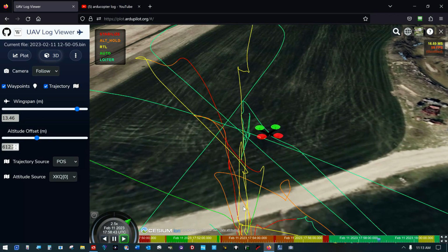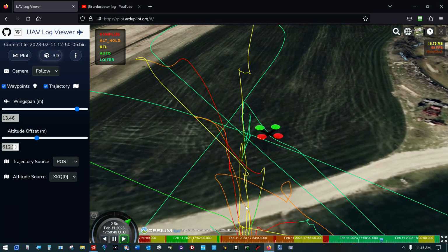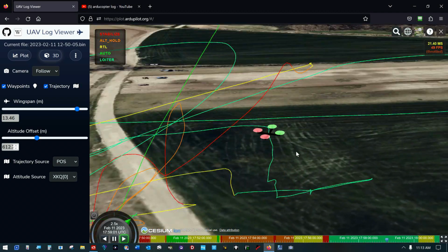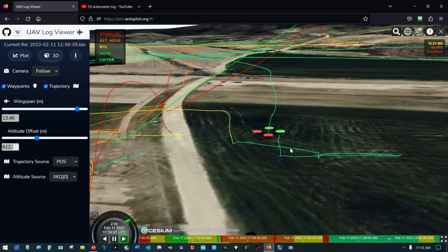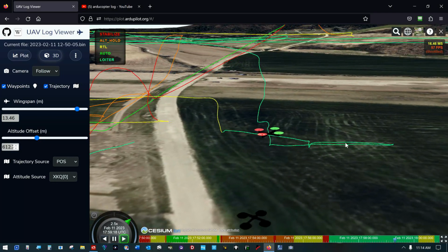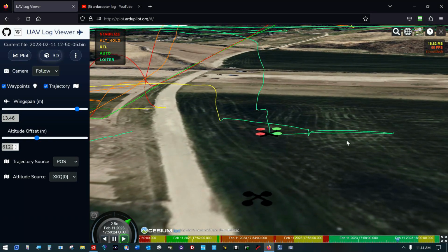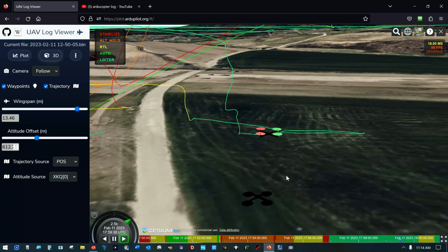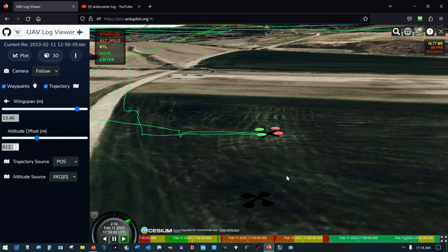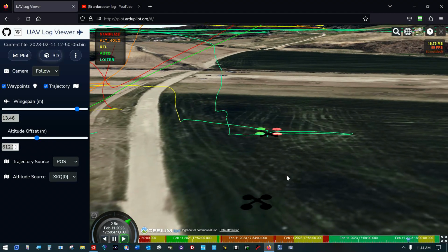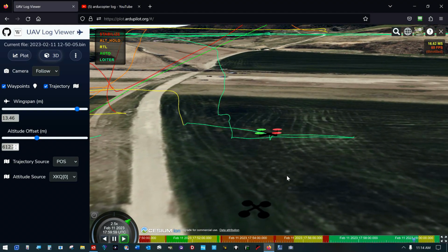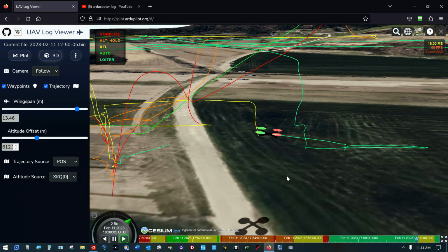This is where I started to check the battery, because I was thinking the battery was low. And this is one of the problems. I didn't know. So I took it out right here and was kind of flying it right here, hoping it was going to fail safe at any moment. You'll see this in the other things. And right here, the battery started getting mushy. That's the reason for that little dip there. The battery started getting mushy, but I couldn't get it to go into fail safe.